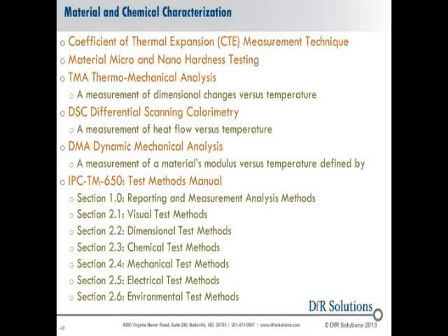There's actually several hundred evaluation procedures in there for everything from your visual test methods, your dimensional methods, your chemical and material and mechanical and electrical and environmental test methods, all at the various levels of different electronic components and materials that we will rely on as we're doing failure analysis to see if the failure is because the part wasn't fabricated right or strong enough.